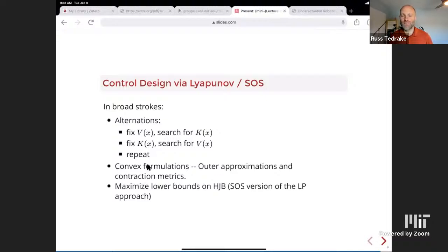Yeah, you're making this easy for me. That's coming up for sure. That's something we've definitely done. So the picture is you have some limit cycle, and that also has a region of attraction. We have to define the notion of orbital stability, because limit cycle stability is slightly different than trajectory stability, but we'll talk through all those. Yes, and yes, you can do it. You end up solving for a periodic Lyapunov function that goes along the cycle, and you try to show that it converges to the cycle.